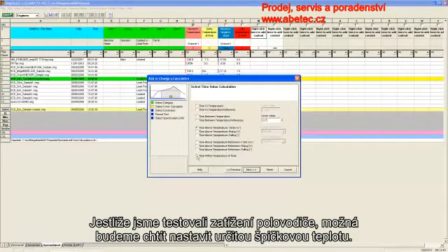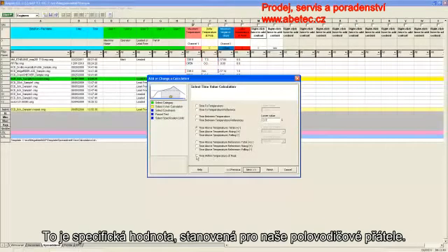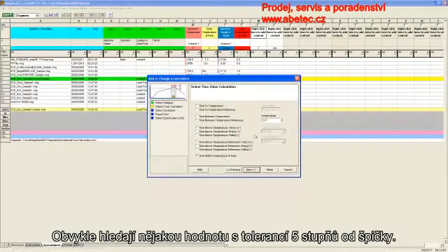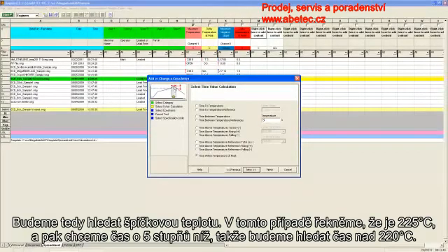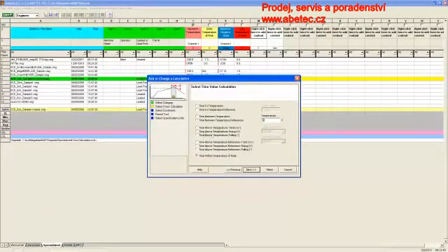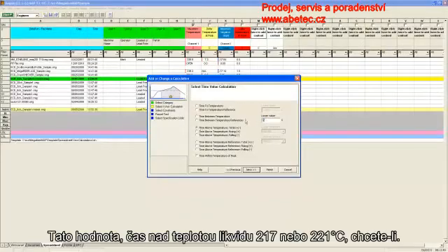If we were doing semiconductor stress testing, maybe we want to be within a certain temperature of peak. This is a specific measure that was put out for our semiconductor friends. And usually they look for a value within 5 degrees of peak. So it'll find the peak temperature. In this case, let's say it's 225. And then we want the time above 5 degrees below, so it'll look for the time above 220 in that case. But for this value, time above our liquidus temperature of 217, or 221 if you like.